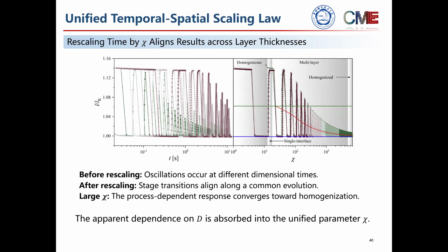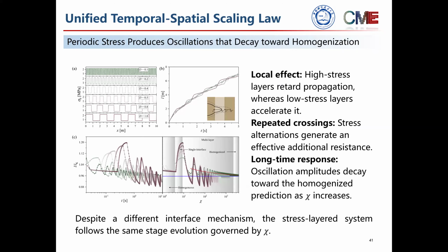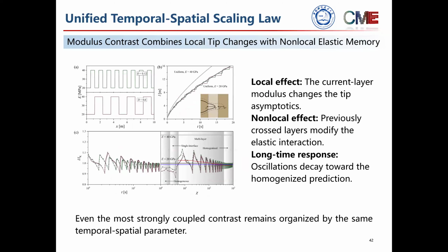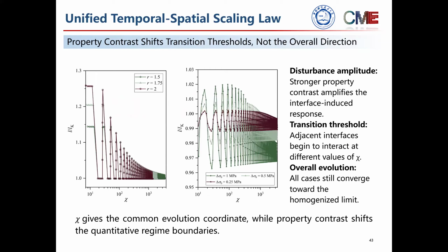The important result is that the boundaries between propagation stages are organized by the same dimensionless evolution coordinate. We can also test the problem using the periodic in-situ stress contrast and the periodic elastic modulus. Their results are the same.